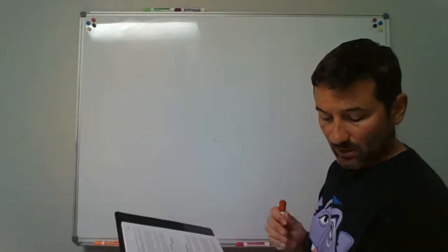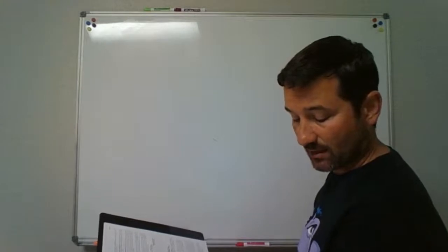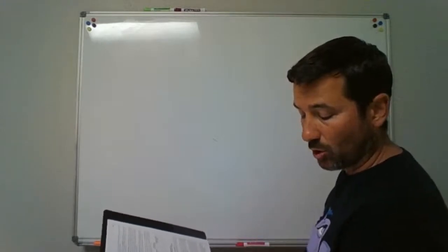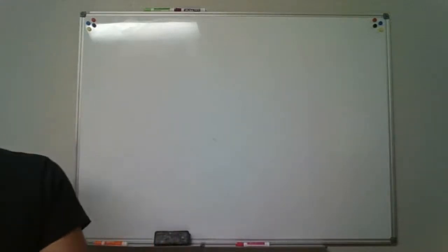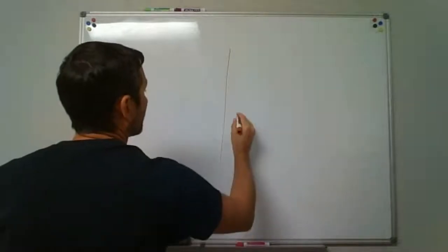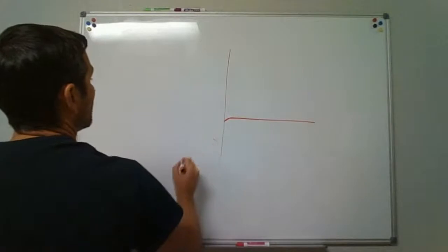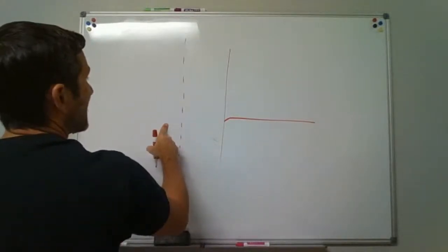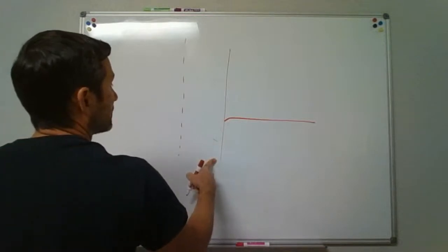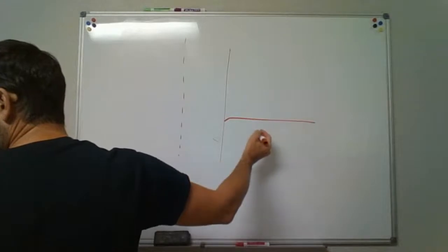Okay. The lower end of each relief vent shall connect to the soil or waste stack through a Y below the horizontal branch serving the floor. Horizontal branch, it serves the floor. You've got a vent, this is the vent stack going up. Here's your soil stack or waste stack. You've got it coming across here.